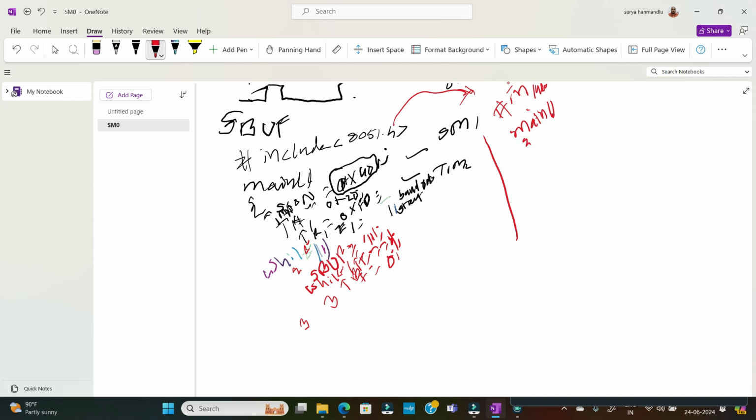This SCON is equal to, you have to write 50H now because we want data reception. Okay. So capital SCON is equal to 0x50. Terminate it. Then we have to select the timer, right? So first let's select the timer mode of operation. So we have selected timer 1 in mode 2. Same step.